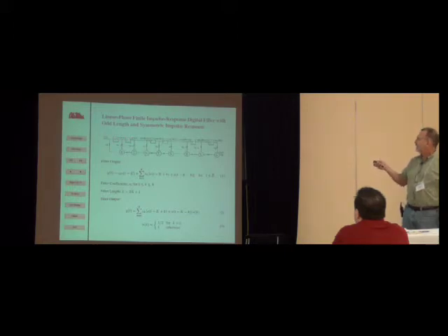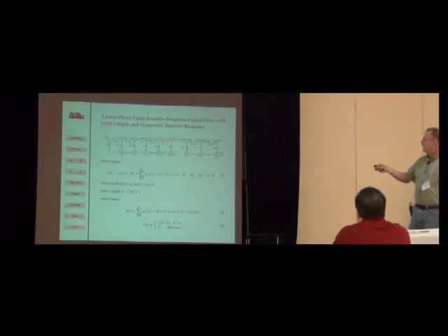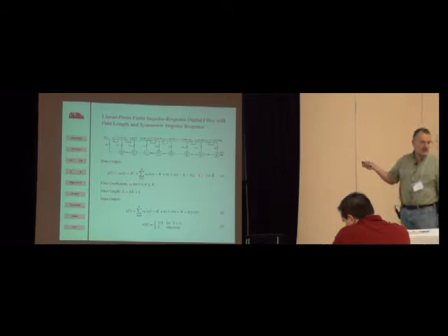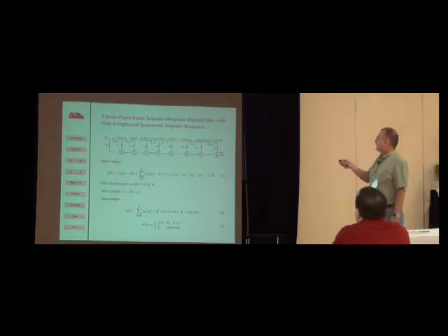So you've got the delayed input, and then the output you get by taking these various delayed forms, multiplying by a coefficient, and then summing up all of those results to get the output. And so this y of t is also actually a discrete convolution. Here, I've got a filter that has odd symmetry of these coefficients.